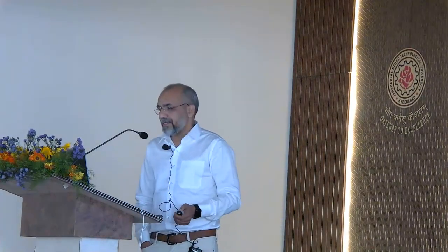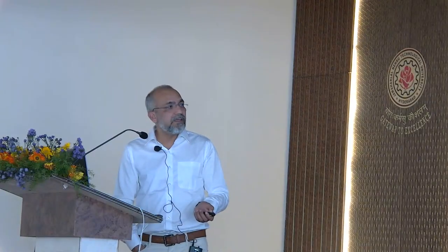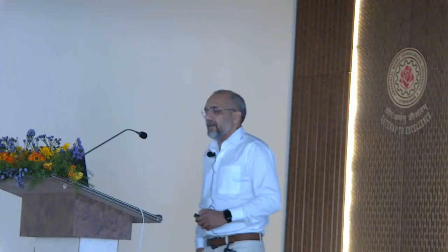As I mentioned, it looks very straightforward. You have bulk material and simply crush it and finally get a fine powder. But there are different steps and stages. It goes from the squeezing stage, then the grinding stage, then fracturing, and then segmentation of flattened particles, and at the end of the day you will have this fine powder.